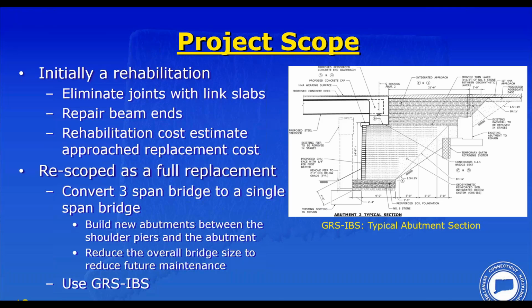Okay. A bunch of questions on that. Looking at it, do you have piles supporting the abutment? No, we do not. We're fortunate in Connecticut. We have a lot of glacial till. We have many places where we can use shallow foundations. When you get closer to rivers, we almost always go on piles because of scour and sometimes poor soils.